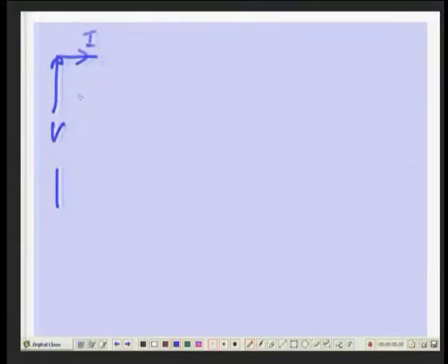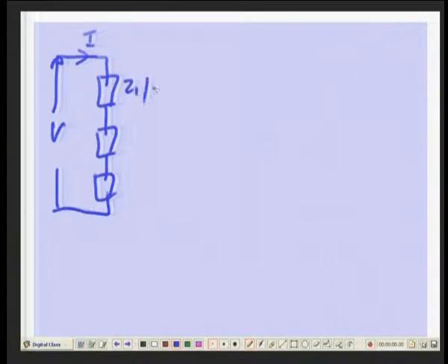Now, actually last class we clarified this. What did we clarify? See, you have two things, you say the same V and the same I. In one case you say it is equal to 3 impedances, Z1 by 3, Z2 by 3, Z0 by 3, agreed. If you take a 3 phase model, and you know what is Z1, Z2, Z0, this positive sequence circuit, negative sequence circuit and 0 sequence circuit.